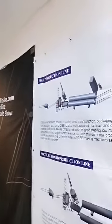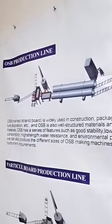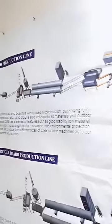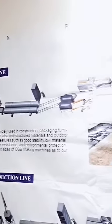materials preparation. For Particleboard, the range of usable raw materials is very wide, like the offcuts of timber, or you can buy the cut-offs or trimmings of plywood, or some rejected plywood, and the branches of the wood, and wood logs. Also in some countries and areas you have bagasse. Bagasse means the leftover, or the rubbish, from making sugar from cane. Then there are rice husks, straw, some rubber wood, and also coconut shell and peanut shell. Many materials can be used for Particleboard.